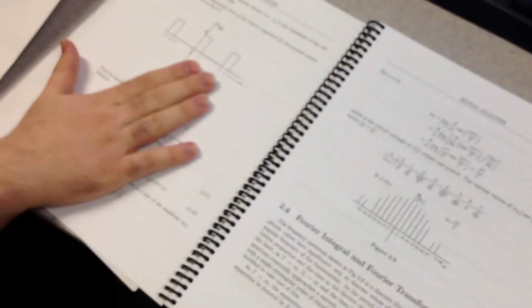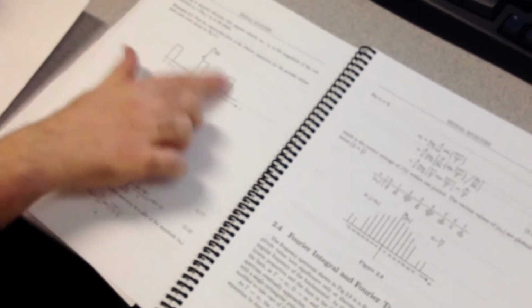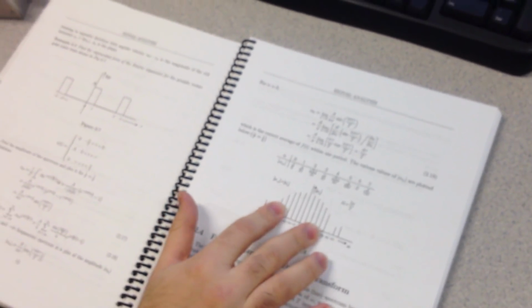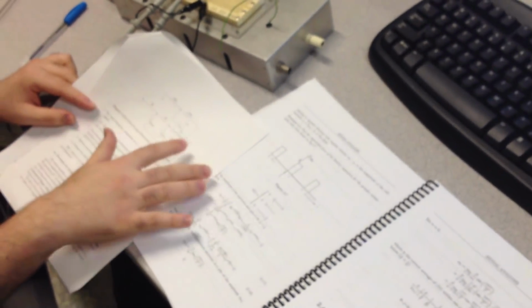This is the same wave we will use. We'll use a frequency of 500 hertz and a duty cycle of 20%. You could change this, but these are the typical values. And this is the input spectrum that we expect. We want to pass this signal through this filter and see what happens to the output signal.